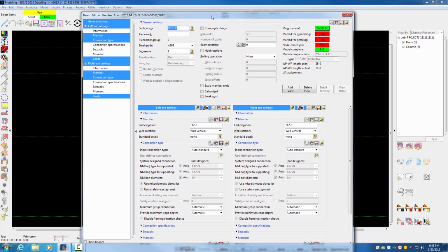As I'm putting in this beam here, you can see section size we put in, piece mark, it's blank. On your drawings, when this plan was created for this course, if the piece marks are showing up on your plan, for example this beam here, W 18 by 35 is an 8B2, do not enter the piece mark as shown on your plans.